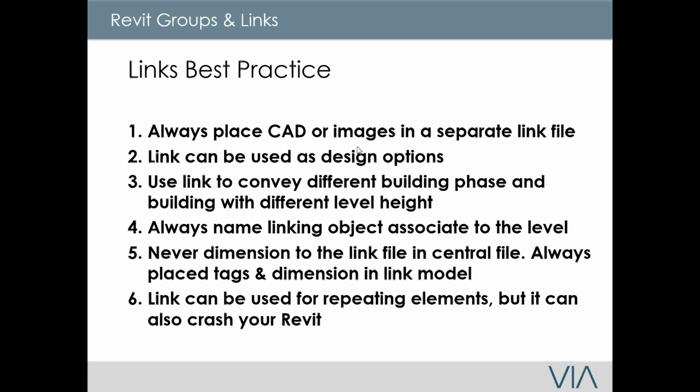The funny thing about links is that when you tag the link file and the objects are unloaded, the tags are still there. But when you reload that link, sometimes the tag will not associate to the object itself.